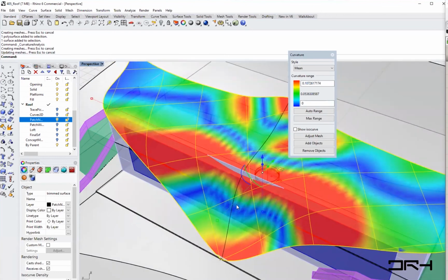But you are right in that there is more engineering information there. For example, if your analysis is all solid green, which is like 0, you know that you can unroll that surface. So in terms of a cylinder, you can unroll it, while this surface, you cannot unroll it without stretching it at certain spots. So that tells you how expensive it is to build that surface.